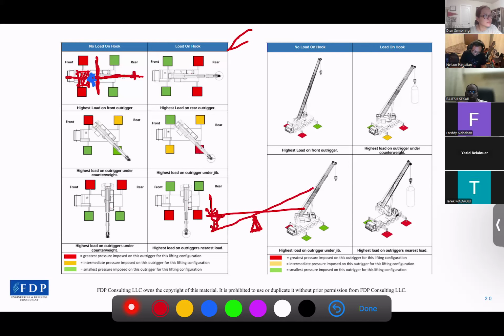But when we put the load at the front here, it will counter this counterweight load so that the COG will start to move to the front here. So actually this is all only about the balance between the front load and the rear load.